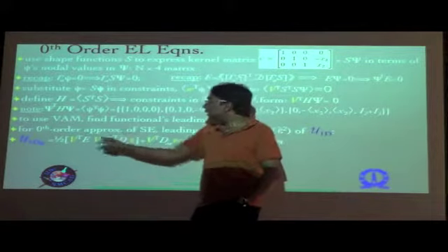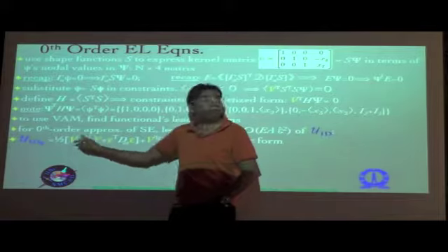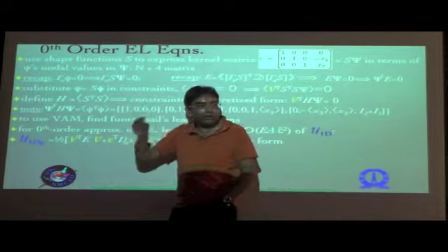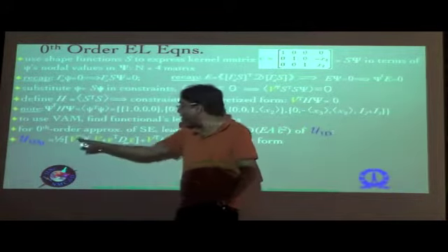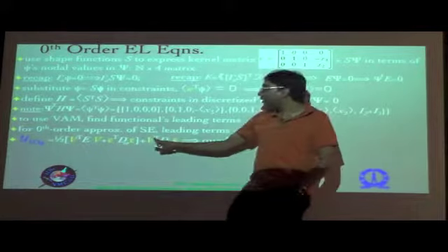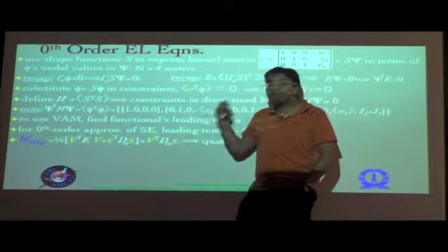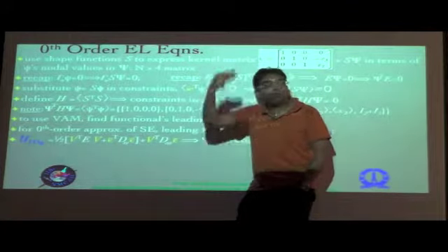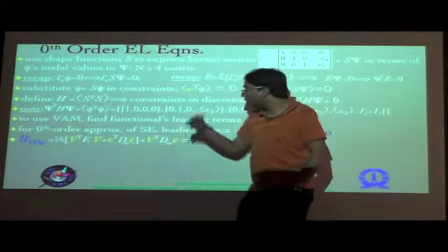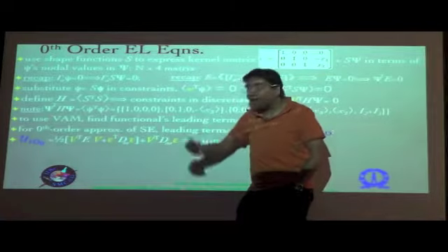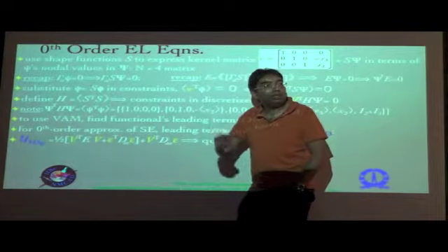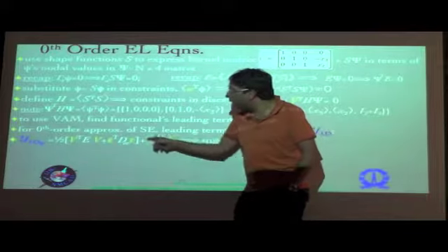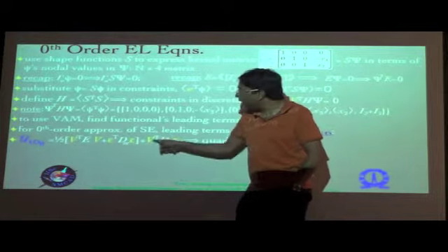So if you look at this, one has a bilinear form. If you remember the forms that we introduced, the linear form, bilinear form, etc. So it's a bilinear form, and the other is a linear form. These epsilon bars are assumed to be known right now because we have fixed x1. Epsilon bars are all functions only of x1 and of course time, but basically at a given cross section and a given instant of time they are fixed. So basically the only unknown is V, and that's a linear form.